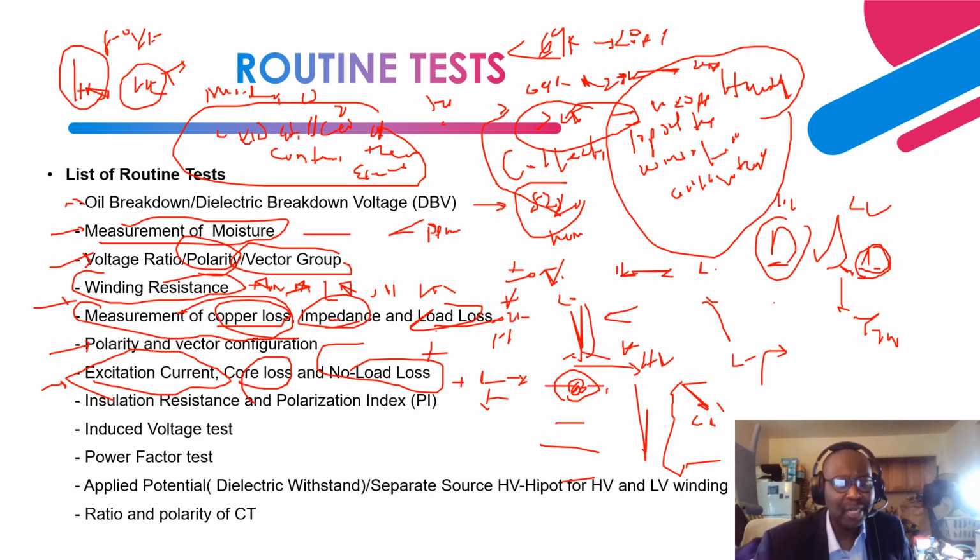And in evaluating the excitation current, you look for a pattern, right? So you have phase A, phase B, phase C. The pattern of phase A and phase C excitation current should be the same, and phase B should be higher than both, right? Usually the testing is done for each tap level, right? So anytime that you see not a routine pattern, just an abrupt change in excitation current, then that calls for concern and further testing to be confirmed. Next is insulation resistance testing, right?